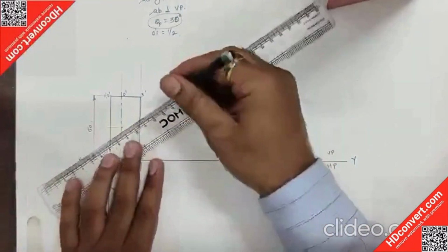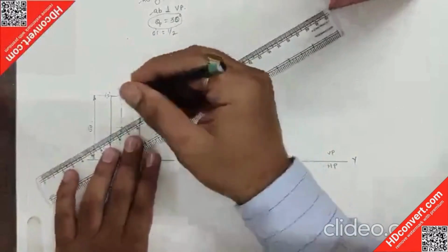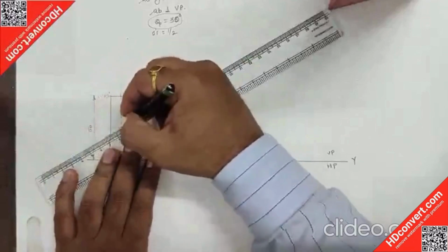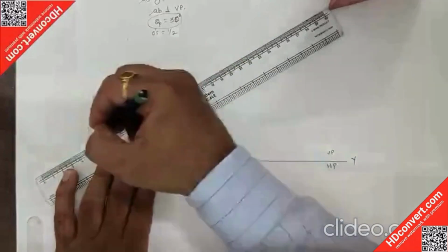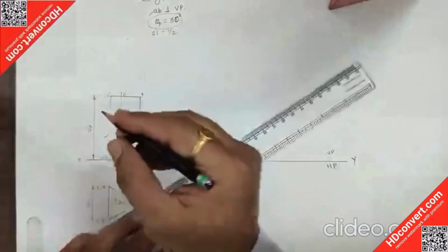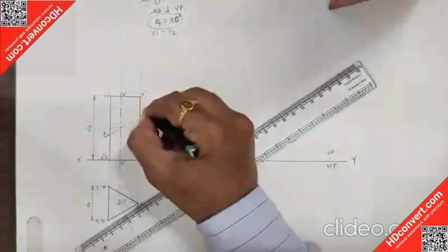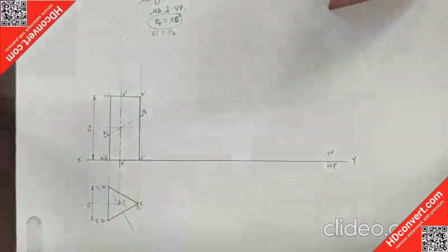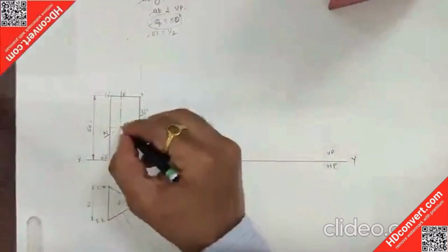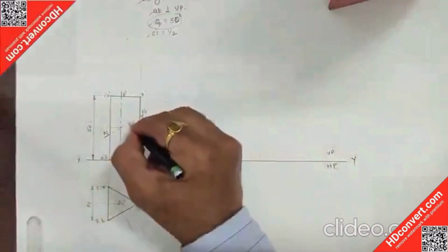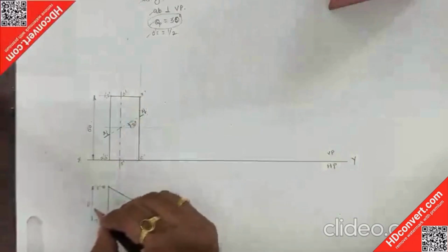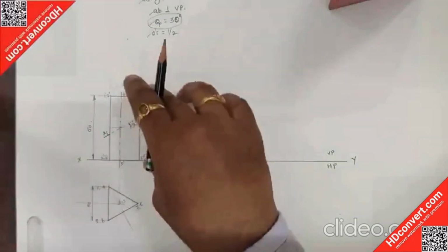And this is the cutting plane, drawn with long dash, short dash, long dash, short dash, and the ends with thick dash. Suppose A. This is showing the cutting plane. Up to this stage we have utilized all the parameters or given data. Now we know that the base edge size is 30 mm and the axis height is 60 mm.